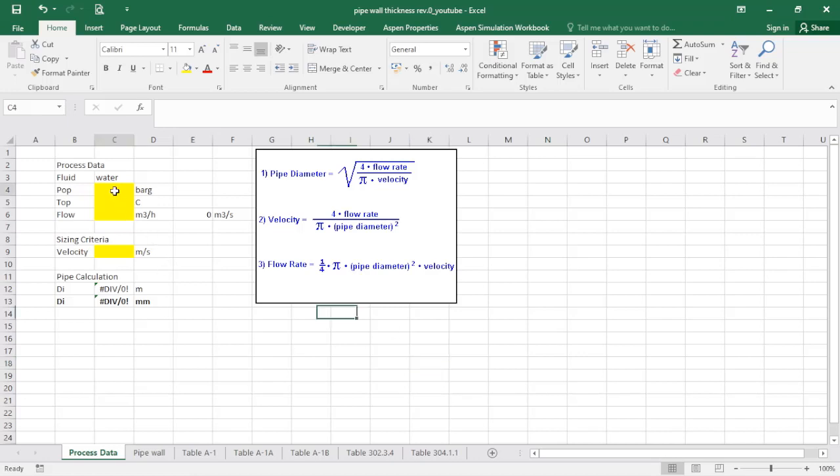So in this case, my requirement for operating pressure is 2.5 bar G, and as I'm dealing with cooling water, my cooling water needs to be at 28 Celsius degrees, and my flow, for reference, in this case will be 65 cubic meters per hour. With this initial information, the chemical process engineer can start doing the preliminary pipe sizing.